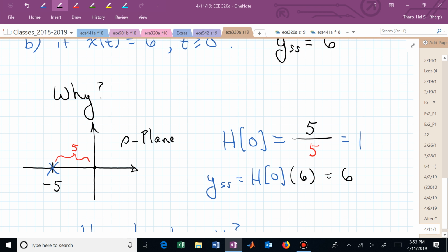So we're asking, how does this system respond at DC when s is equal to 0? And we can figure that out by saying, well, what poles and zeros do we have, and what contribution do they create or influence? How do they influence our response? Well, the pole is going to give us a factor of 5 at DC contribution. The numerator started and remains at 5, so at DC we have a DC gain of 1.